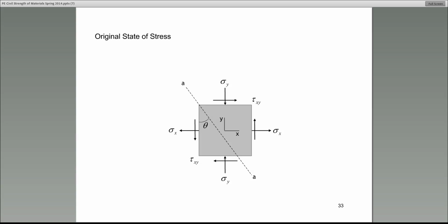Let's assume that this square that I'm showing represents the state of stress at a given point. And for demonstration purposes, we show a large square, but please understand this is a very, very tiny point on an actual beam, actual structure. All right? So when you look at the state of stress, we have these sigma x. This is, let's say, the bending stress that we calculated using the Mc over I equation. Or we have sigma y. This is the bending stress in the y direction.